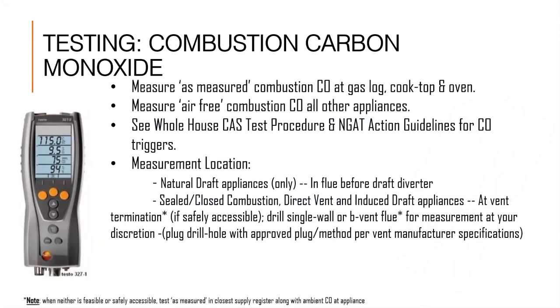Earlier in the presentation, we showed the slide that had all of the combustion testing items listed on one page. The last 3 of those were about how and where we measure for carbon monoxide at various combustion appliances. They were testing for ambient carbon monoxide at an appliance, combustion carbon monoxide inside the flue, as well as kitchen appliance carbon monoxide and measuring ambient and flue gases.